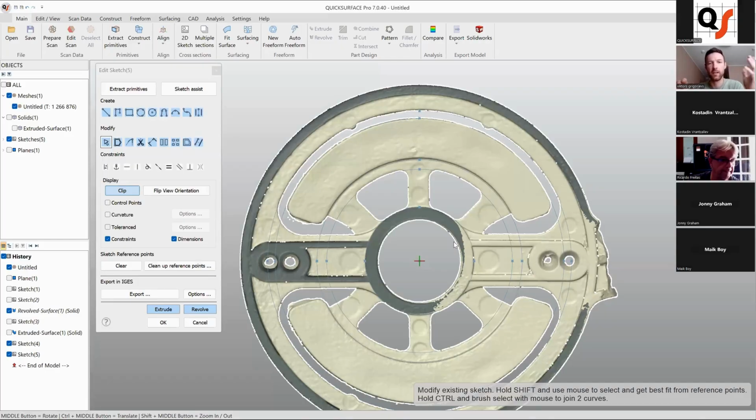We're going to have one exact geometry all the time, so we will have perfectly vertical walls where we need that. This is a more advanced approach. You don't fit your entities all the time according to mesh points, because results can be slightly different every time. That's why I would suggest using a technique like this.